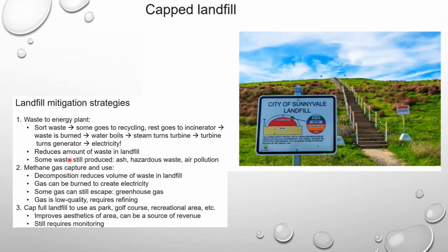For methane gas capturing and use, I did not emphasize the third bullet here, that some of the methane can still escape, and it is a greenhouse gas, which is bad, bad, bad. And I did show you that there's primary, secondary, and tertiary treatment. So it goes through multiple levels of cleaning that gas because it's really low quality methane. So it's going to require a lot of refining for us to use it in its pure form.